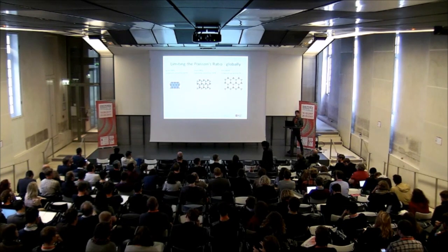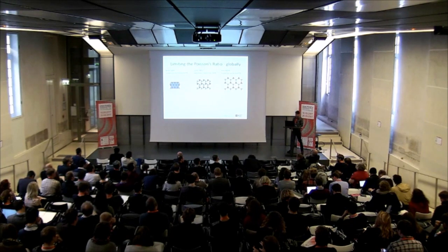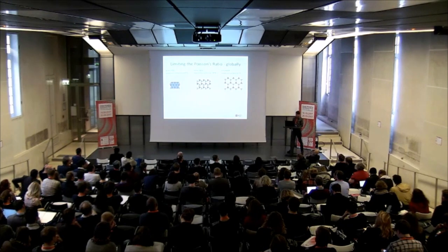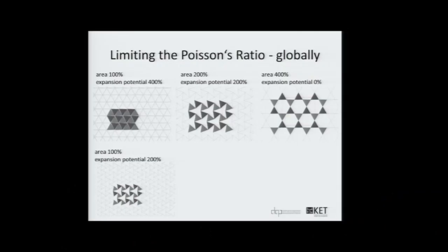To improve the control over the deformation process, our innovative approach is to use already modified patterns as our next starting point. Instead of straight cuts, where we started on the upper row, we're performing polygonal cuts in the flat material. On the left side, they are both based on the same mesh, resulting in an auxetic structure with a lower but clearly definable potential for maximum expansion.